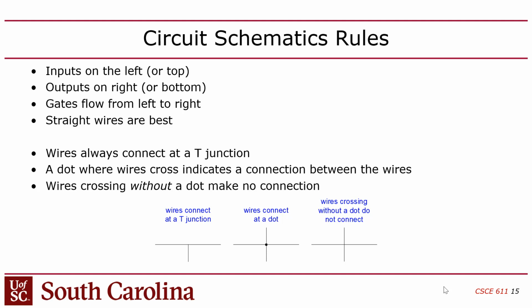Generally speaking, those blocks will have inputs on the left and outputs on the right, and you connect those blocks together with wires. Again, in Verilog you don't make any drawings. You define all these connections in text using structural Verilog. But when you represent it in a design, it's often done graphically, right? So you have to be comfortable looking at a block diagram and being able to write it in SystemVerilog, structural Verilog.